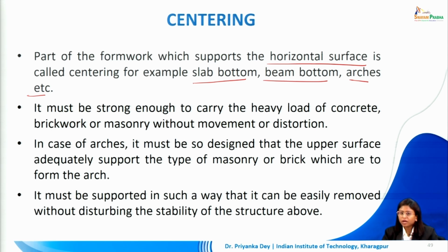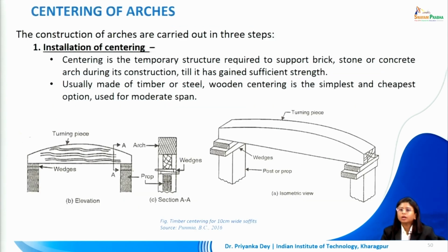Now in case of arches, it must be designed so that the upper surface adequately supports the type of masonry or brick which is being used to make the arch, and it must be supported in such a way that it can be easily removed without disturbing the stability of the structure above. We had studied the centering of arches in detail when we were learning about masonry.